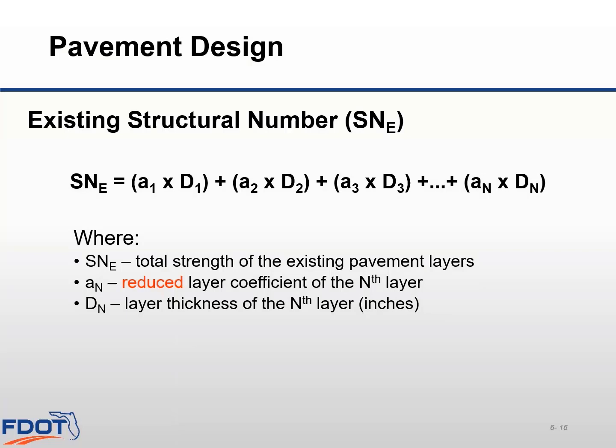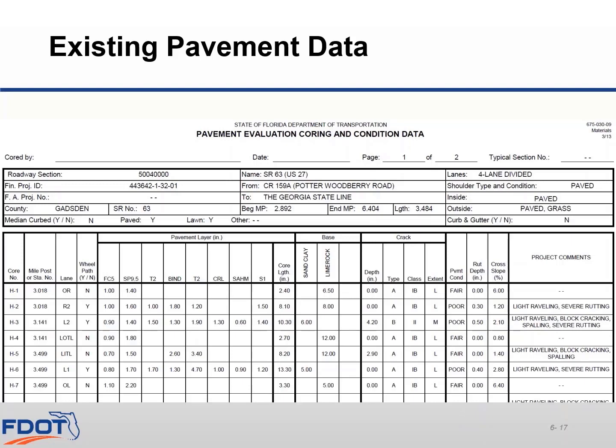When you review your pavement survey and evaluation report, you, as the pavement design engineer, will need to determine the average layer thicknesses that exist on your roadway. So remembering back to your pavement coring report, you'll need to review this report in its entirety and group the pavement cores into appropriate locations, typically by lane or by roadway direction, such as eastbound lane cores and westbound lane cores. This will depend on how many lanes you have.